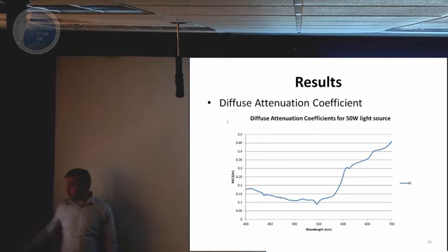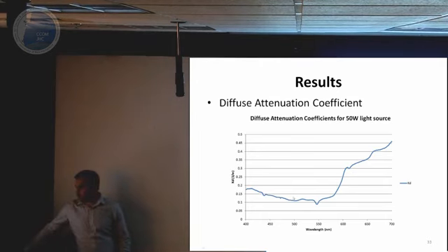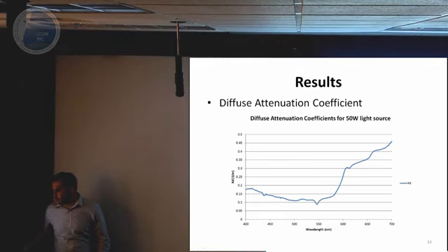What we want to get from this plot is the least attenuation, because we want the maximum intensity. If you look at the range from 500 nanometers to 550 nanometers, we see that the attenuation is the least in this region. So we are getting to recognize our hardware, getting the specifics of the hardware. We want the hardware to be based on this region.